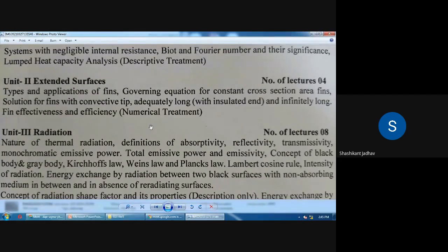Okay, small capacity compressors, transformers of electronic equipment, then electrical motor bodies. So these are the applications where we have to use the extended surfaces, and because of that maximum heat dissipation into the surrounding takes place, and because of that the life of that particular component will increase.